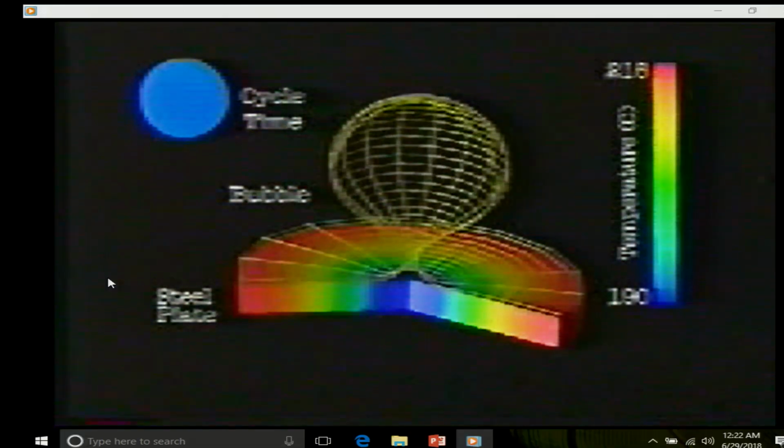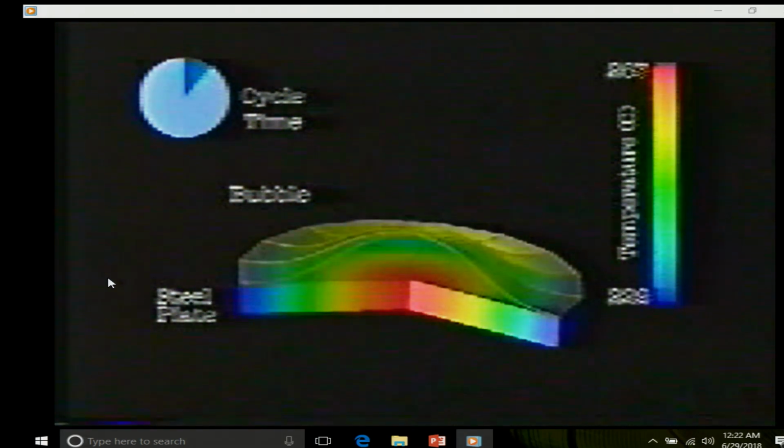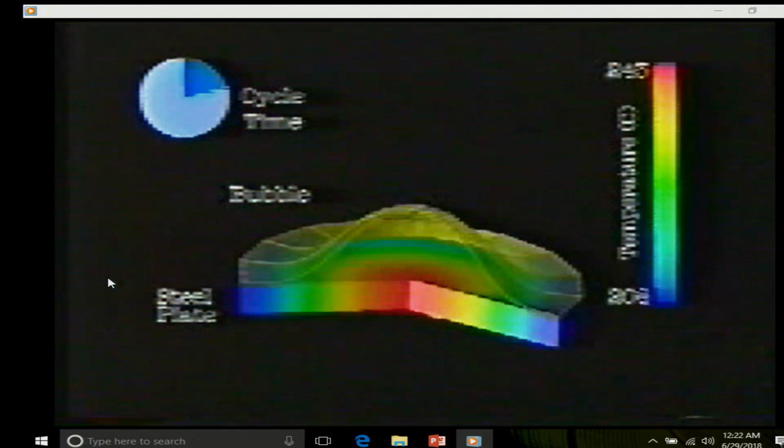Then we looked at our model, where we made a copper heater versus a steel heater, and what we found was that in the copper heater the width of that cold spot was almost double. The reason is copper has a higher thermal diffusivity and thermal conductivity, so it tends to give you a bigger temperature spread, whereas steel has a lower thermal conductivity and lower diffusivity, so that cold spot is thinner.